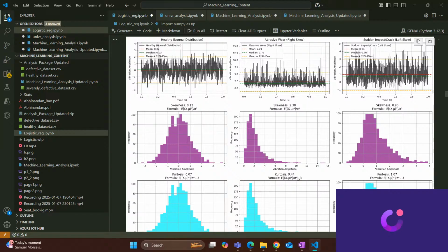So now coming to the values to be decided, whether it is going to be a failure or not purely depends on the domain knowledge. As I gave an example, there's a video from NPTEL where they show the gear failure and decide the kurtosis factor for that, which they decided should be 6 for gear failure for a certain system based on the experimental analysis, right? So based on that they can say okay, for different data, if the kurtosis level is greater than 6, then most of the gear systems might fail. That comes by experience and domain knowledge, as well as with experimental and test kind of correlation with the data.